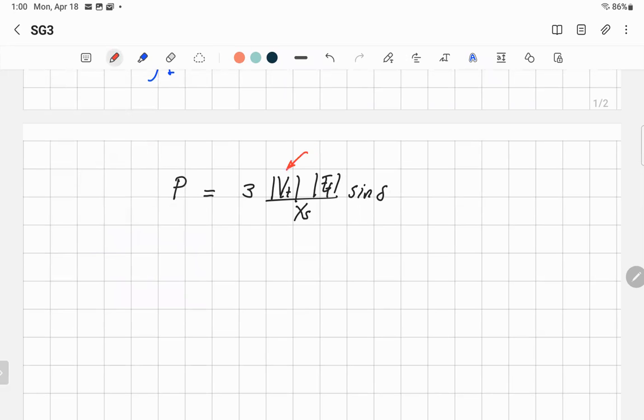No, we just said in the beginning of the lecture, when you have an infinite bus, you always keep the voltage constant. You want to keep this voltage 110 volt, right? So that's constant. What about the reactance? Does it change? No, constant. And the power, constant, because you said that you keep the prime mover moving. So what is changing here? Two things, EF and delta.